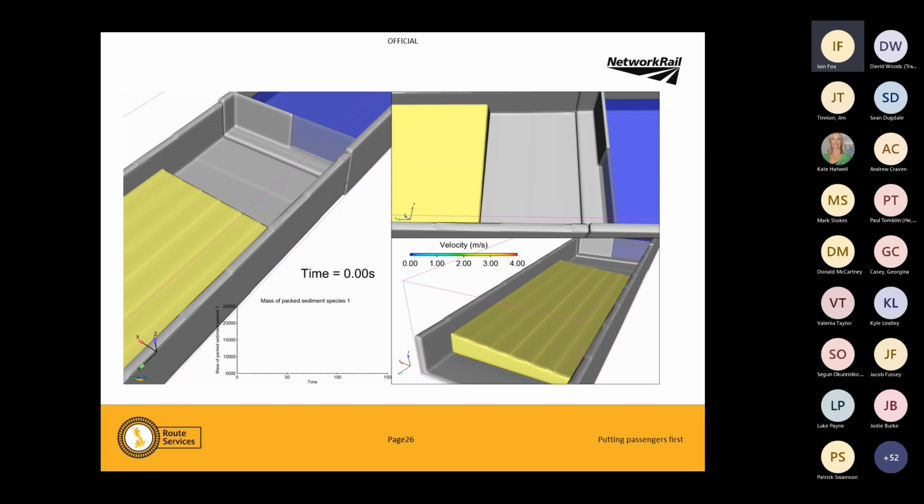And the Australian government said, well, that's great, but what happens is they clog up with sand. As the tide comes in and out, bed deposition, as we've said, it drops sand on here. And we currently pay a guy with a shovel to come and clean all this out. Is there any other way that we can do it? So we looked at this and went, okay, how about you split your gates into 2, you hold a bit of water back, and then you open one of the gates and effectively deliberately scour that sand away.